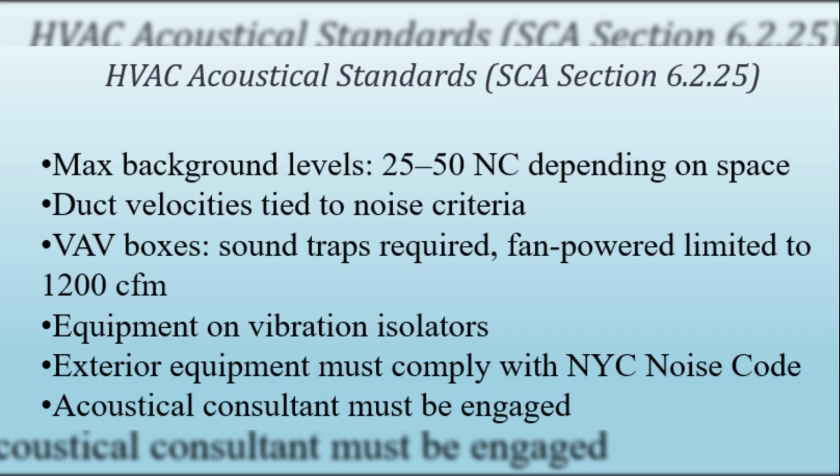Noise and vibration isolation measures are mandatory. All equipment must be mounted on vibration isolators, with seismic restraints applied according to NYC codes. Ducts may also require spring or neoprene hangers for additional isolation, and airtight flexible fabric connectors must be used at equipment connections. Exterior mechanical equipment is subject to both the NYC Mechanical Code and the city's Noise Control Code. That means rooftop units, condensers, and outdoor fans must comply with strict noise ordinances enforced by the Department of Environmental Protection. Finally, an acoustical consultant must be engaged during design.